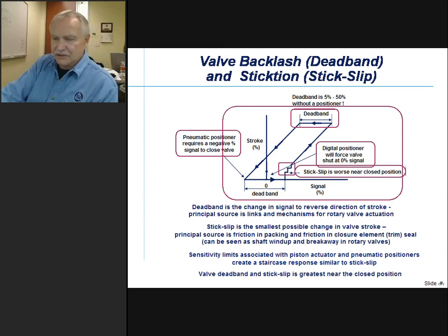Well, and the other thing is, by eliminating that -10% limit, you could get the valve off of its seat quicker, even though you have anti-reset wind-up limits that are helping you move through that region of -10% to 0%. Still, you're going to be a lot quicker if you don't need to set your low output limit at -10%.